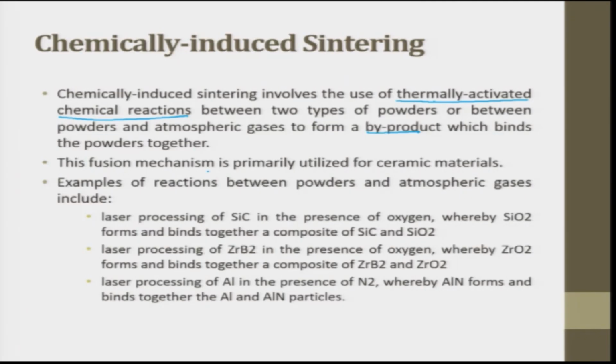This fusion mechanism is primarily utilized for ceramic materials only. Examples of reaction between powder and the atmospheric gas include laser processing of SiC in the presence of oxygen, where SiO2 is formed and binds together the composite of SiC and SiO2.